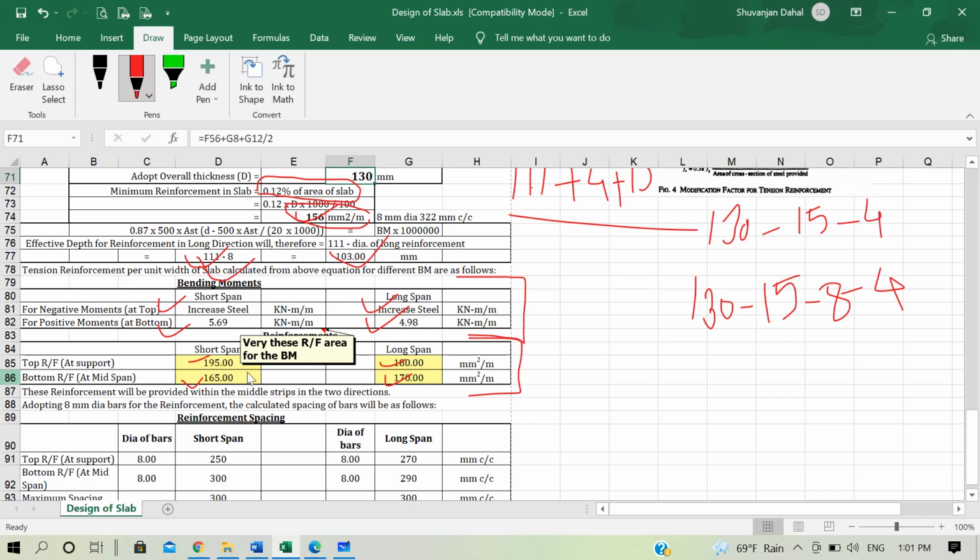If using that area of reinforcement, our bending moments are larger than what we acquired at first, using our formula for Mx and My with bending moment coefficients alpha x and alpha y, that is, if we get the value of moments greater than those actual values of moments coming onto them, then it's okay, and the value of the moments shown here is the value of those same moments that we got previously.